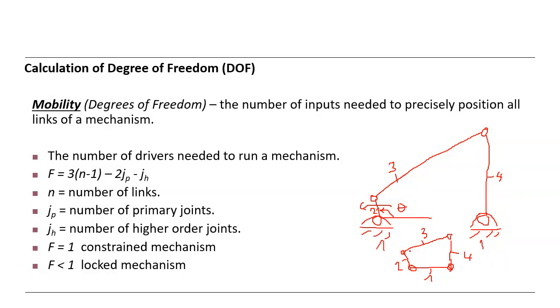So if we fix one of them, like 1, then we have a mechanism. This is not a kinematic chain anymore. Then it is a mechanism like this. But if we don't fix any one of them, it's a chain, a kinematic chain. So that means we can ground member 1 or 2 or 3 or 4.